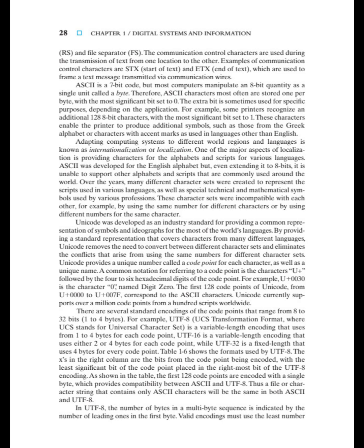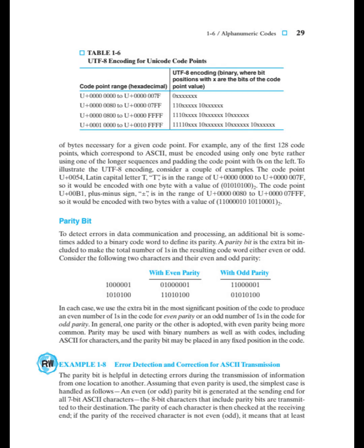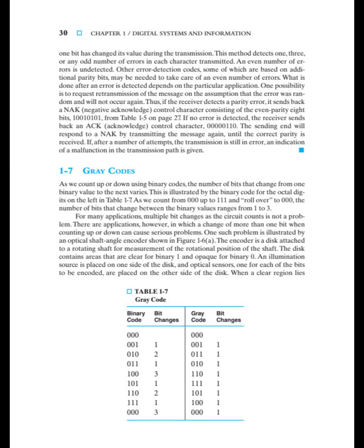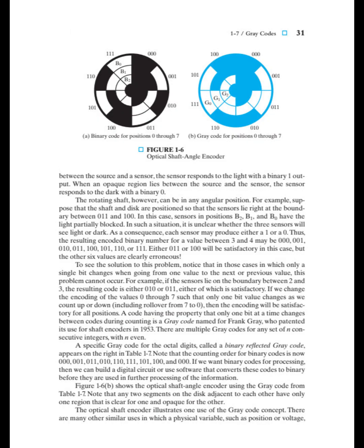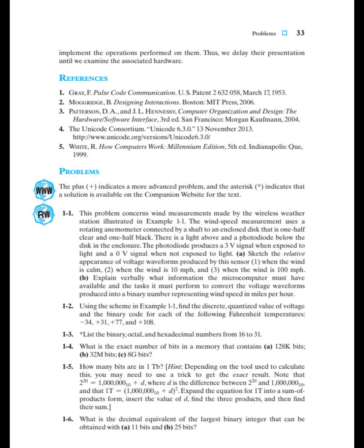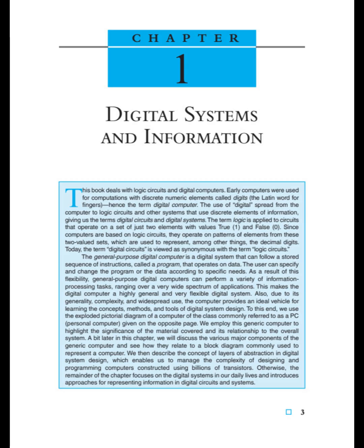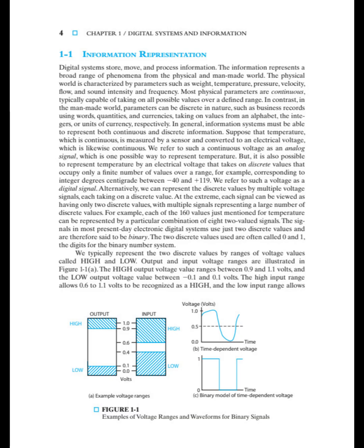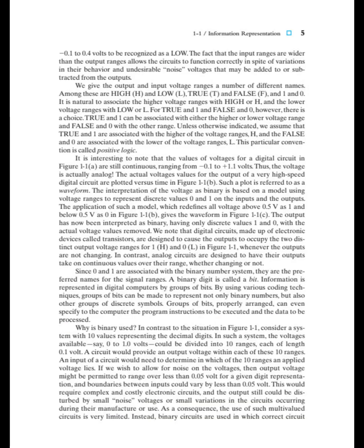Right. But why just two? Why not, say, 10 distinct voltage levels? We could directly represent our decimal digits. Think about trying to have 10 distinct voltage levels to represent 0 through 9. You'd be dividing the voltage range into tiny slices. Any noise, any variation in the components could easily push a signal into the wrong level, causing errors. So unreliable. Exactly. A nightmare to design. So binary, just two well-separated ranges, high and low, makes it so much simpler, more dependable. Much more. Less room for errors.